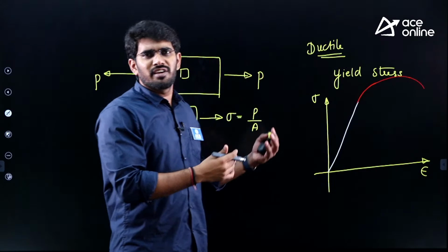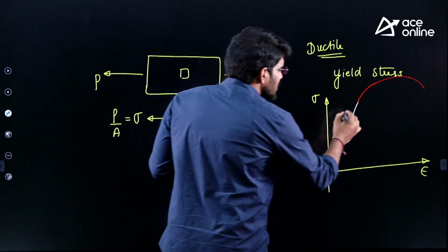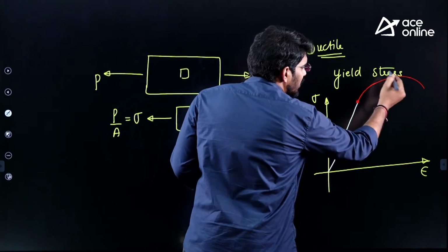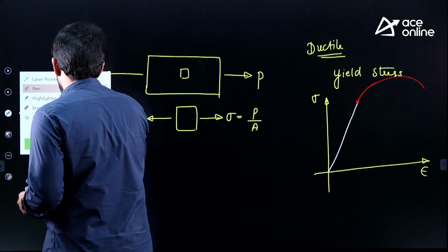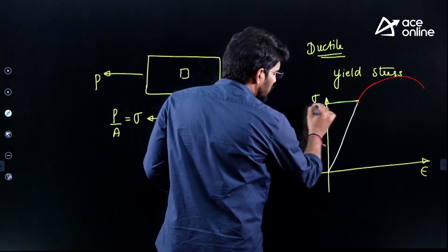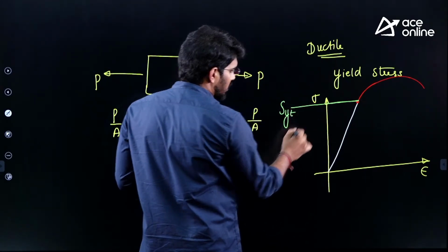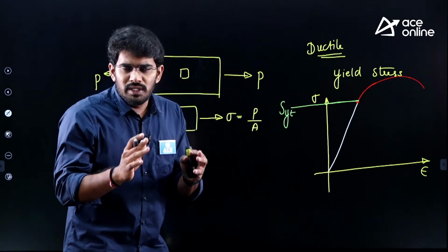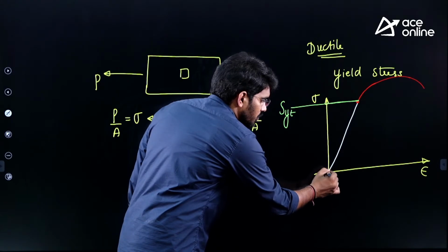This is a kind of material where there is no yielding phenomenon. Here, this is the point where it is trying to enter into the plastic region. So if you are applying stress on this material, you need to apply only below this stress. Let me assume that its value is represented as SYT. We know that when a particle is loaded, it will be loaded from 0.